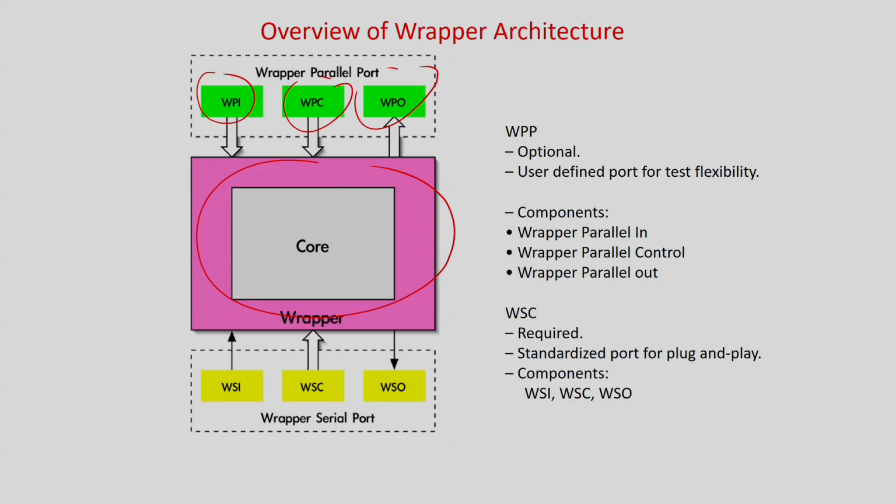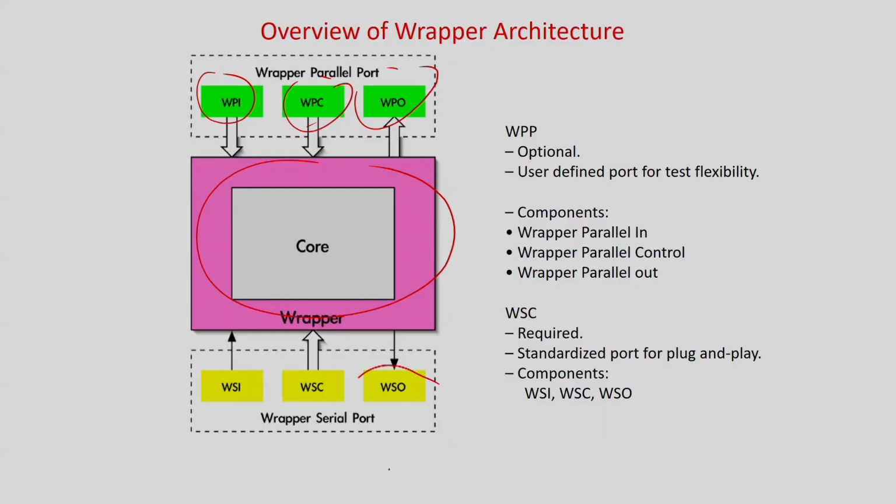So WPI, WPO: wrapper parallel input, parallel output. Multiple pins you can apply to give the test patterns. Here the TAM will be of higher overhead because multiple patterns can be given. And there is a control. Control, as I told you, is when to go for test mode and when to apply functional mode, etc. But this is a must.